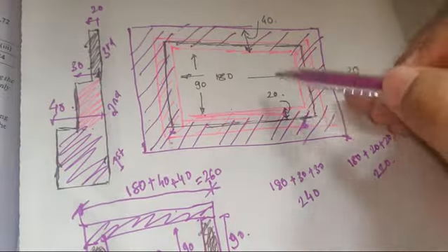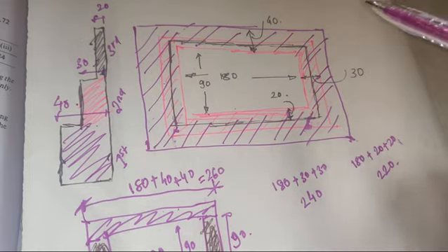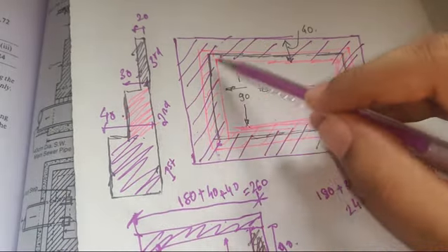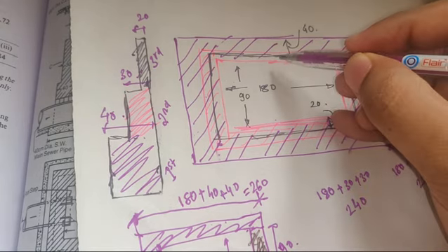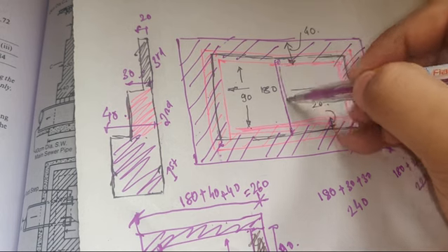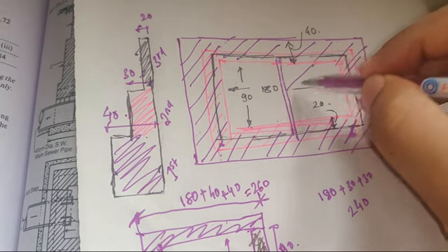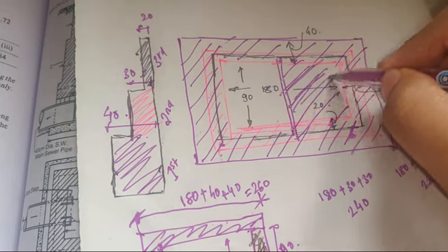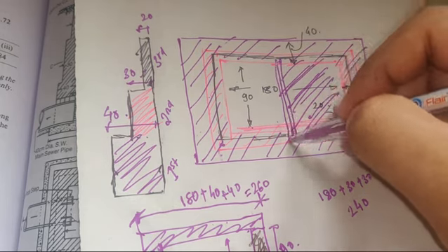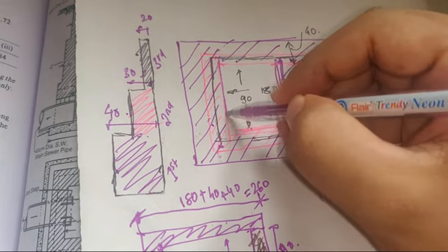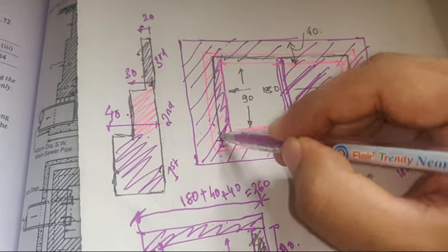So we got this quantity. And as I was saying here, the 20 centimeter wall is resting over the 30 centimeter wall. So what I did was I considered this as resting throughout, but the 20 centimeter wall is cut at this portion only. It is only provided up till this portion. Then they have provided an RCC slab here. So your 20 centimeter wall is only up till this length. It is only running from this length to this length, right?